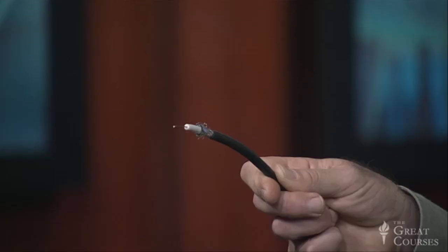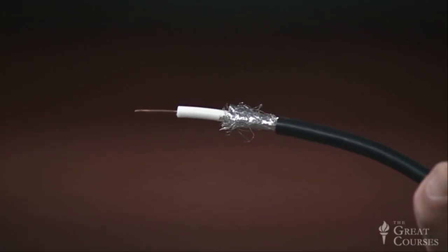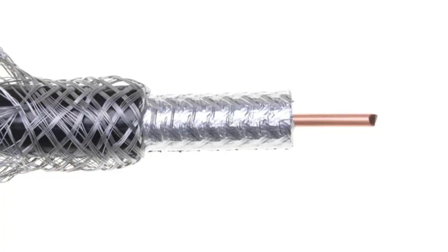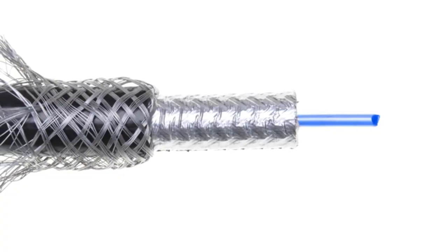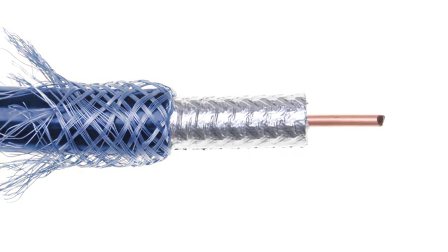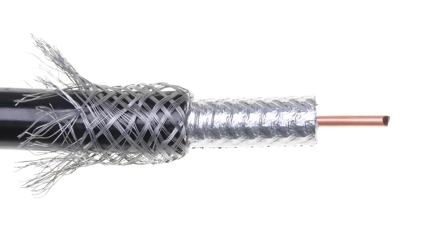But it was actually developed in the 1920s as a replacement for twisted pairs in the inter-exchange trunks of the PSTN. Coaxial cable, or coax, consists of a heavy copper core surrounded by an insulating plastic sheath, a woven metal shield, and an outer protective jacket. In a circuit, the copper core serves as the conductor and the woven shield as the return path. The great advantage of this arrangement is that the electromagnetic field generated by the conductor is largely confined within the shield, resulting in less power loss and greater resistance to interference.